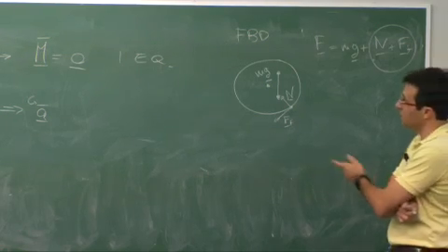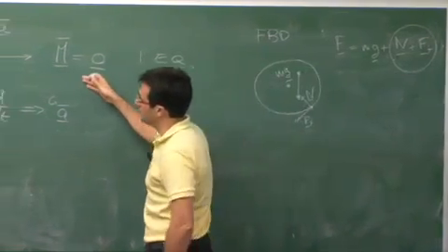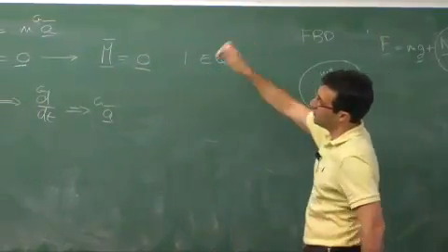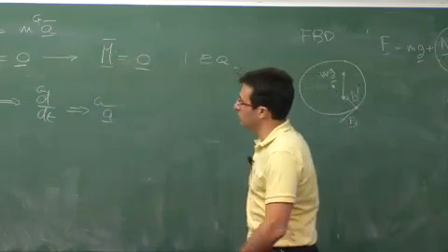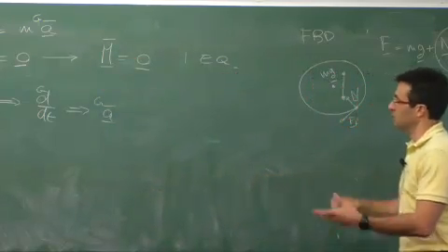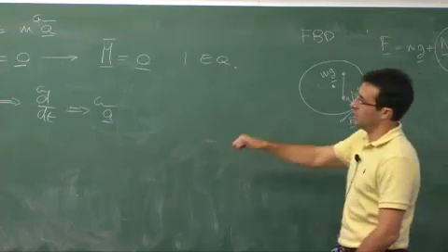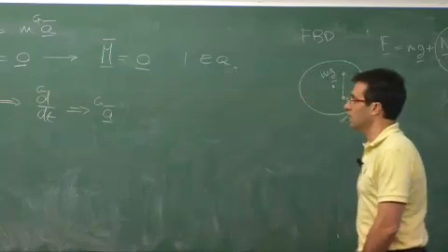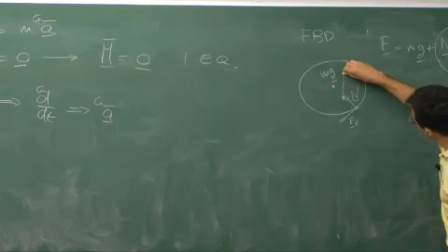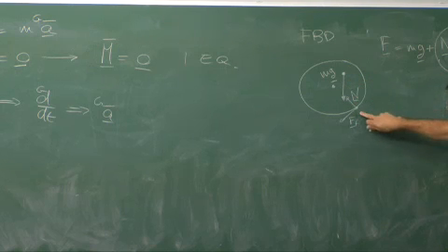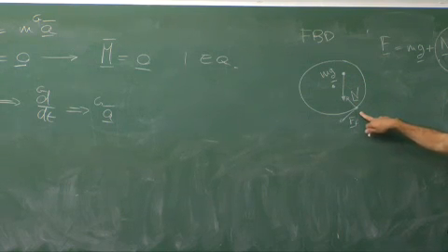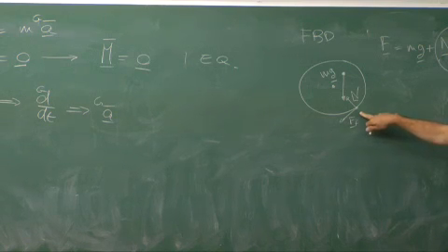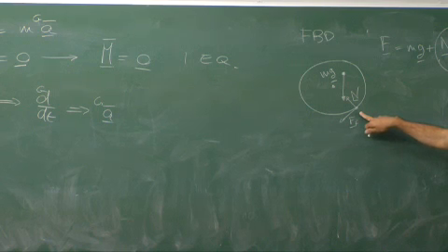And so I will need a third one, and the third one will give me the additional equation. How many do I get? Well, I already told you, I get 1, because when I start doing, all the forces are in the plane of the board, all the position vectors are in the plane of the board. When you start doing your cross products, they will all be along the EZ direction, plus or minus, I don't know. But this will be only 1 equation. And if you do it with respect to the center of mass, which is this point here, the gravity will not contribute, but these 2 will be there. So that's your third equation. Now you have 3 equations, and you can play around and probably eliminate your unknowns.